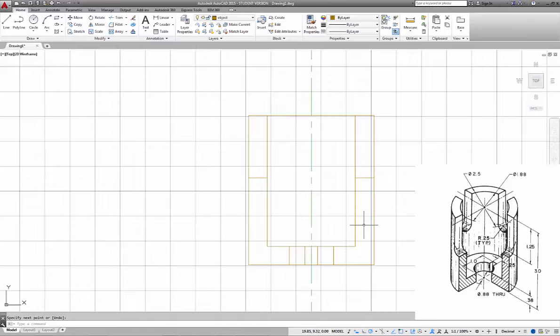You know what? I bet you we forgot to put hidden lines on our layer properties. But we'll find that out in a minute. So now we've got to section this area, so we actually get to see what the sectioning lines look like. So I'm going to switch over to the section layer, and there's this tool here called hatch, and hatch is what the section patterning looks like.